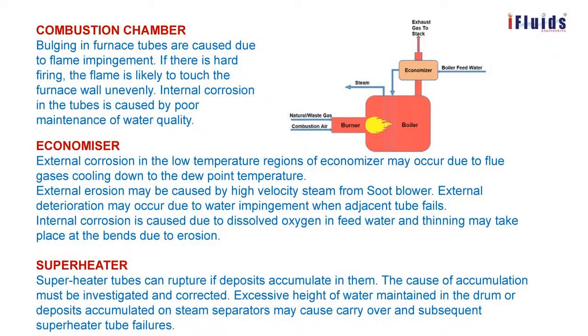to erosion. In the superheater that we already discussed, superheater tubes can rupture if deposits accumulate in them. The cause of accumulation must be investigated and corrected. Excessive height of water maintained in the drum, or deposits accumulated on steam separators, may cause carryover and subsequent superheater tube failures.